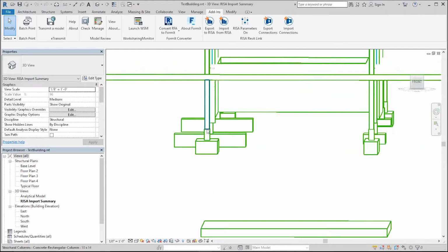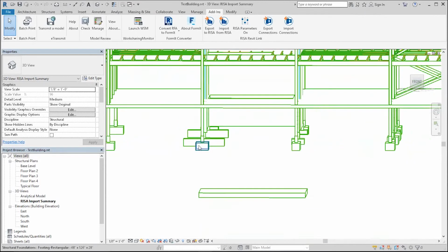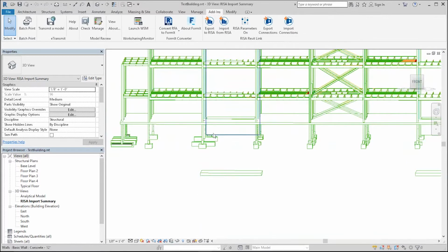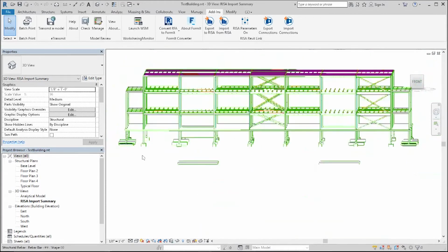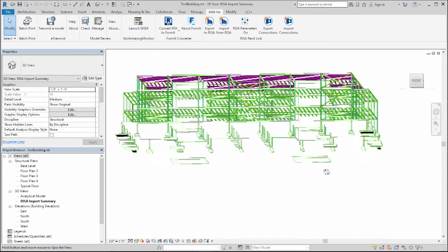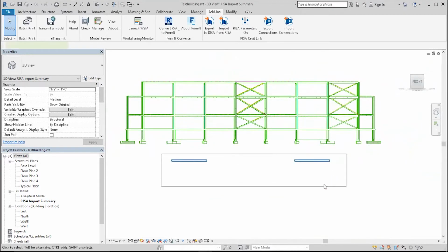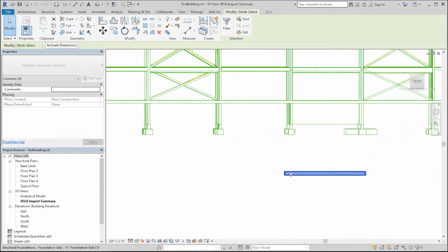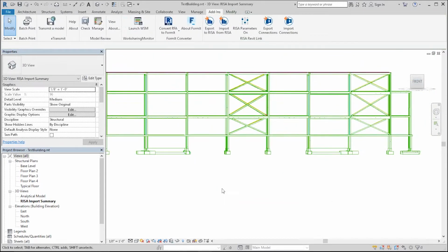Footings are pretty easy. They always sit at the base of a column. But a foundation slab can be connected to multiple levels, things like that. So what we've decided is just to send it all the way to the bottom, and then you can scoot this up to the level you want it to be. You would just increase that so everything slides up once you're ready, and place it underneath the wall that you're looking to set it under.